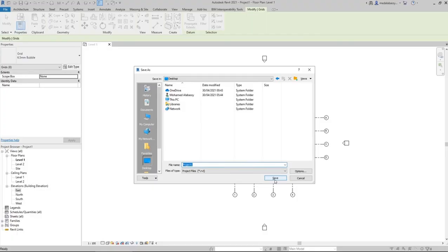The Revit files are not backwards compatible, so the old versions are not forward compatible, so only the newest versions are backward compatible. So version 2022 will open any previous version, but version 2019 or 2020 cannot open an RVT file that was modeled in Revit 2022.